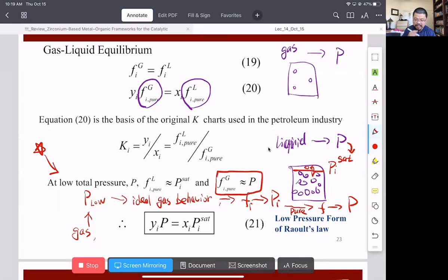On the other side, we are using the same understanding I just mentioned about the saturation pressure. In the liquid phase, molecules at the interface are going to vaporize into the vapor phase to maintain the equilibrium. And we are going to stop this transportation when the fugacity or chemical potential is exactly the same.